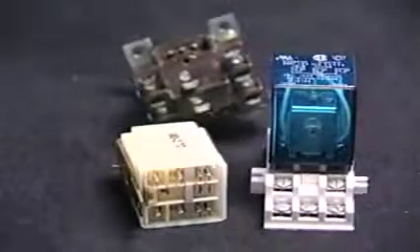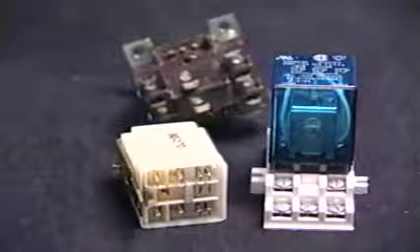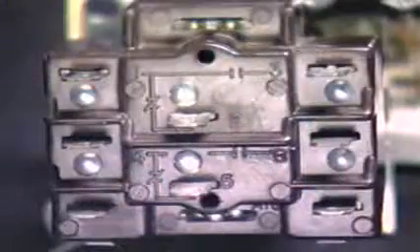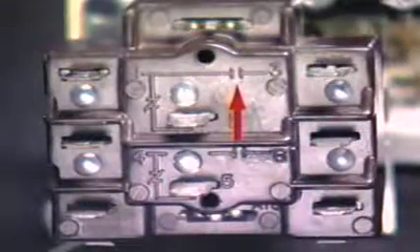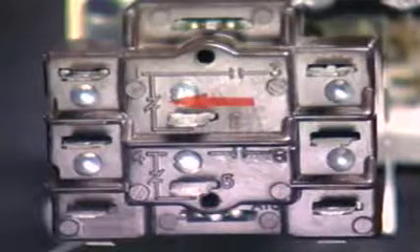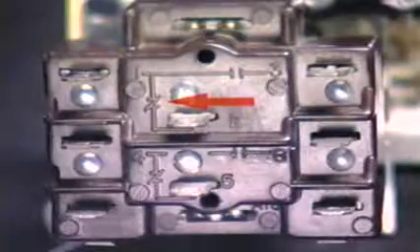Similar to contactors, relays have a coil and sets of electrical contacts that are used to control the operation of system loads. The main differences between relays and contactors are that relays are typically single-pole devices and have lower amperage ratings than contactors. Normally open contacts are drawn as two small parallel lines. Normally closed contacts are drawn as two small parallel lines with a diagonal line connecting them.